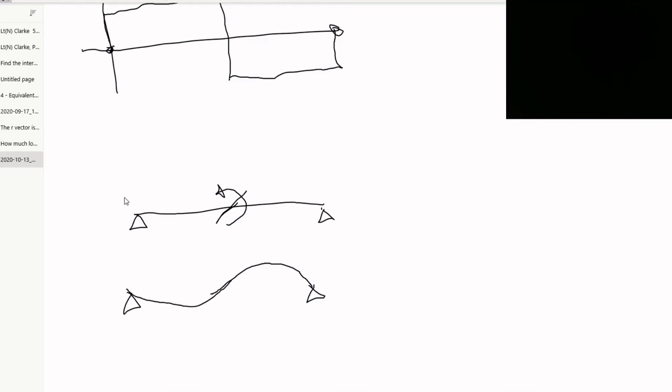So essentially, if we go back to our definitions of what a positive internal moment is and what a negative internal moment is, we're saying that we start out on this side of the graph with our moments being all positive, because again, this is a smiley face on this end, and then it switches over here.